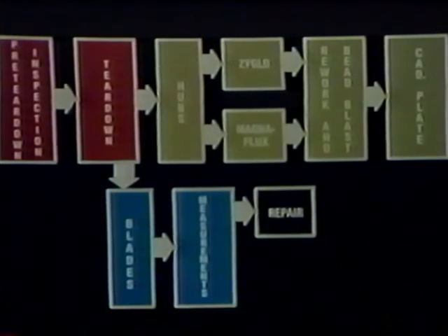Blade repair, for the most part, involves blade straightening, filing, grinding, and repitching if necessary. This photograph identifies a repairable blade. The manufacturer's specifications dictate certain allowable limits from which a damaged blade may be straightened and returned to airworthy condition. The blade seen at the top of the picture is repairable. The blade at the bottom is not.